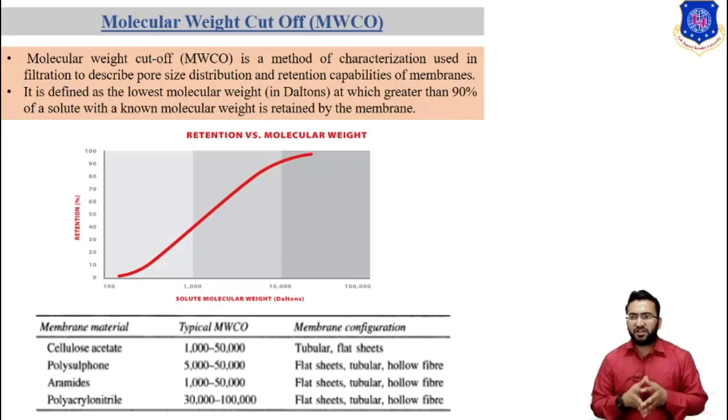To get the entire rejection profile, it is required to have the expected rejection range from 0 to 100% rejection. At the lower end, solutes such as sodium chloride and glucose are used since they are expected to have zero rejection by the ultrafiltration membrane. At the high end of the scale, large proteins like immunoglobulins or blue dextran are used since they are completely rejected by most ultrafiltration membranes. There should be some other solutes of intermediate molecular weight.